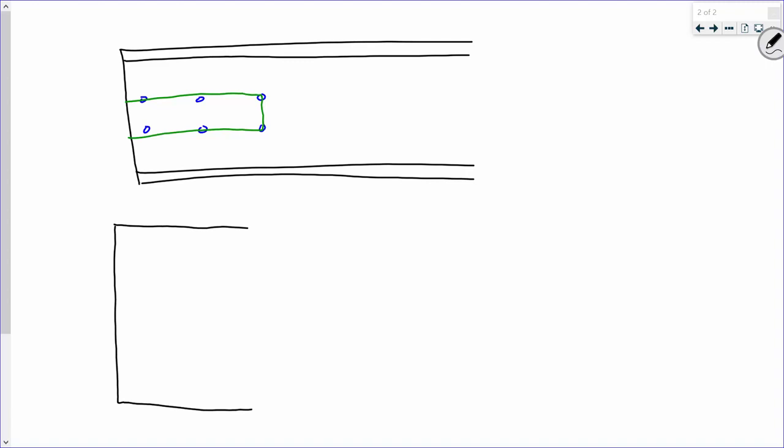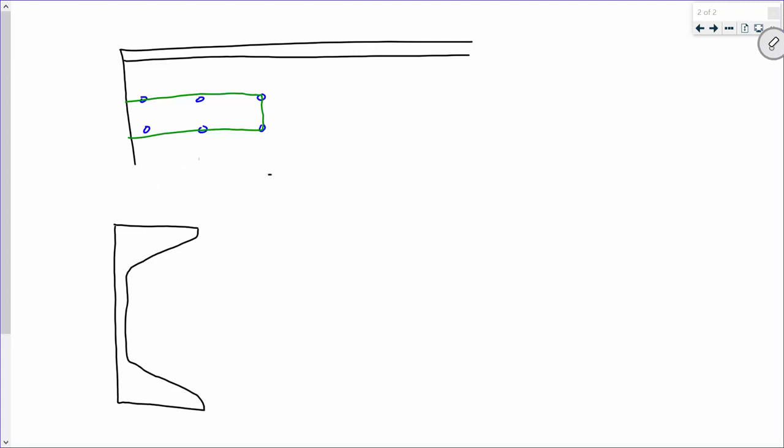Okay, here's what the channel really looks like. That's probably a little wide. The channel looks like this, okay? So it's going like that. And I'm exaggerating a little bit, but I'm kind of getting my point across. The way channels are manufactured, the flanges aren't flat. They're actually sort of on an incline. The flange thickness that it reports in the manual is literally just the average, okay? Now, let me draw this in 3 dimensions, okay? Now, let me draw this failure path again.